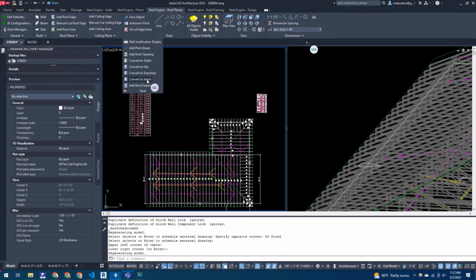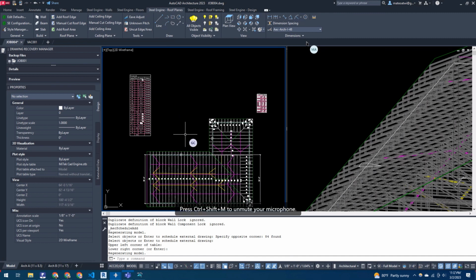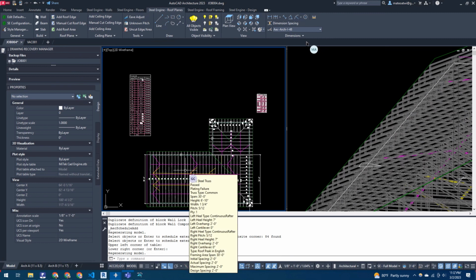But we don't have a dormer feature. So you just have to model a little roof on top of your roof. Will it know to intersect with that other roof? If you tell it to. When you're doing the manual cut roof edge, one of the lines could be in the existing roof, so it shows the valley line properly.